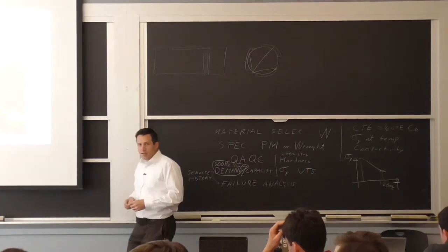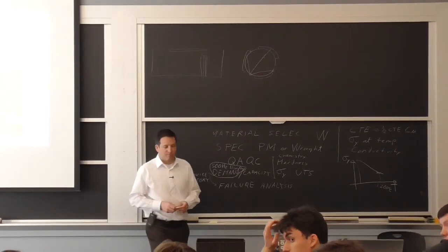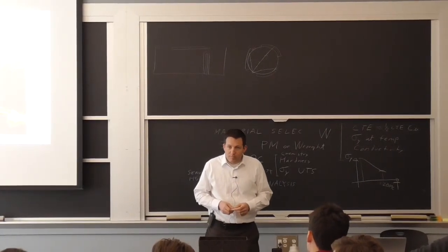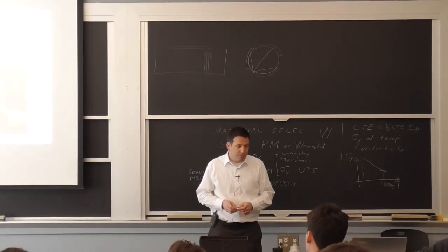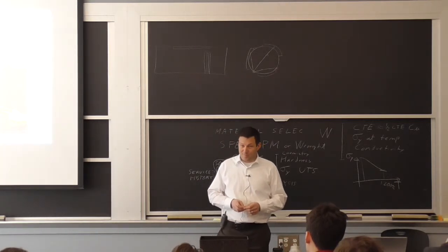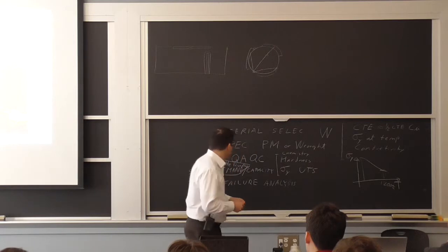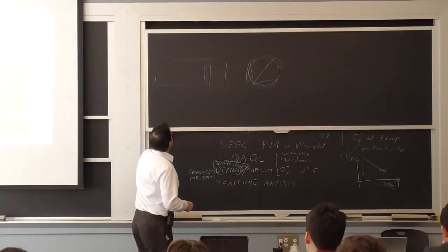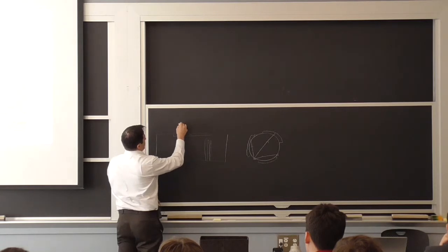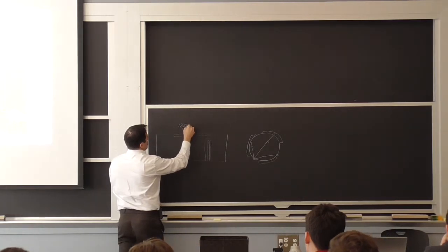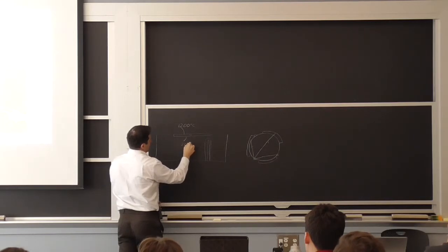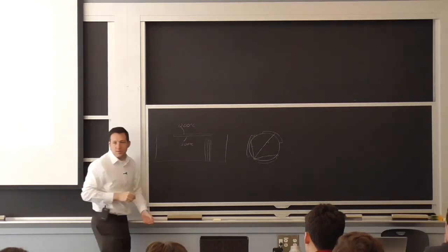Actually, I have a question. I know you said that the heated spot gets up to about 900 degrees Celsius, and you said even up to like 1300 or something. I know that the melting temperature of copper is around like 1100 or something around there. Roughly. How did you guys determine how thick the tungsten needed to be such that the copper would melt beneath it? So you have about 1200 here on the surface, and you only had about 300 centigrade at the interface down below.